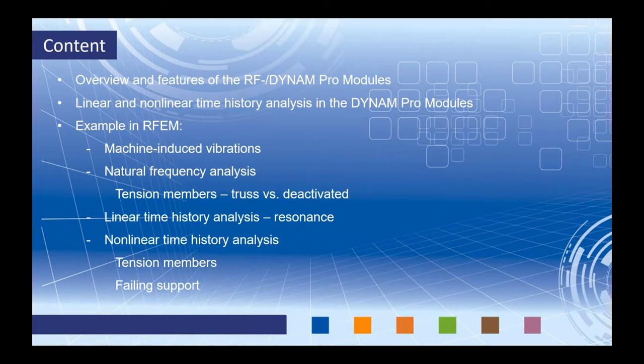And finally, we've recently added nonlinear time history analysis in RFEM. So with this, we'll take a look at a couple different nonlinearities that we can now account for, such as tension-only members, as well as a failing support.